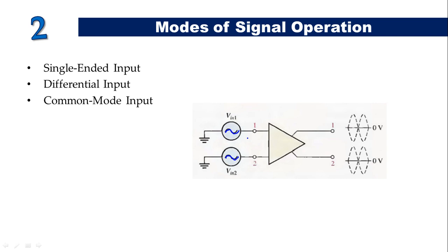So again, when we analyze this, considering each input signal acting alone on the differential amplifier, what happens is that the first one is, of course, out of phase, right? The first is out of phase. Then the second one follows, non-inverting. So what happens is it becomes zero, they cancel each other out in each output signal.